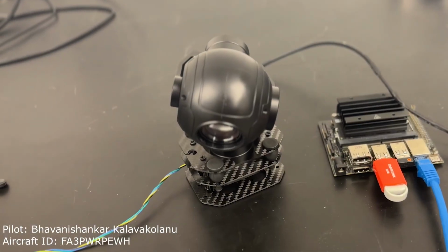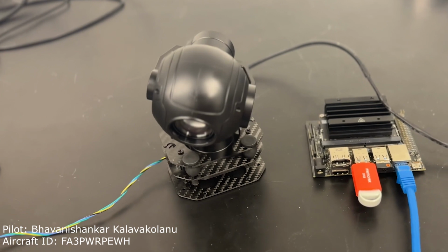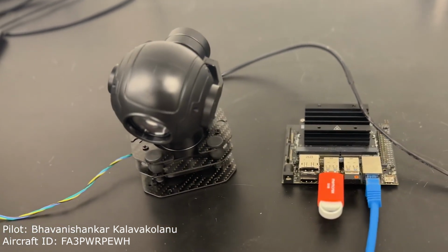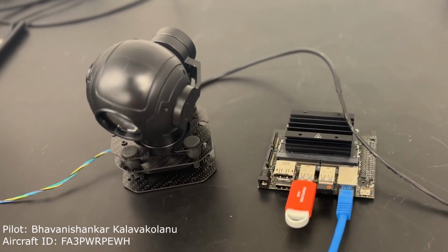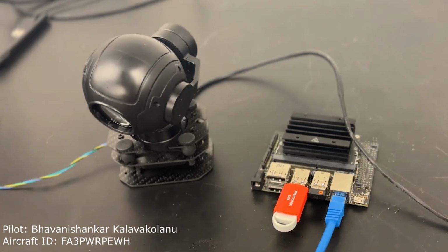The team chose to use the CE ZR10 as the camera system for this year's UAV. The ZR10 was the optimal choice for many reasons aligned with the competition requirements and compatibility with our Pixhawk 6X flight controller. The main feature was the 10 times optical zoom and the 2K image resolution, which ensures image quality remains clear even at high altitudes.